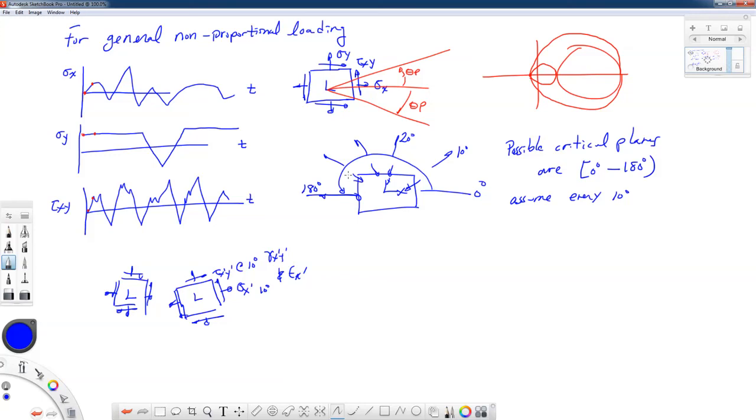A multiaxial cyclic plasticity model is the tough part, in my opinion, in all of this, because we need a very good model that doesn't overestimate strains, or if we're measuring strains and calculating stresses, doesn't overestimate stresses, because they can have a big effect on our calculated fatigue life. So one way or another, we need a way to relate stresses and strains.